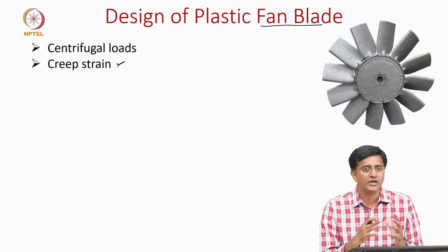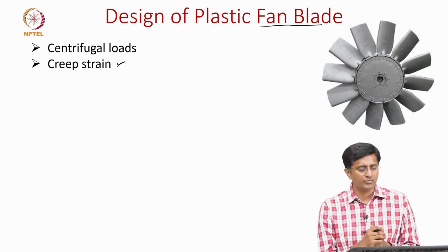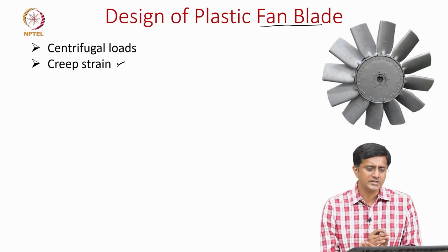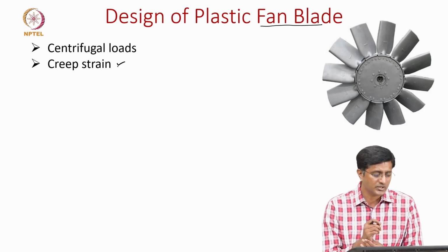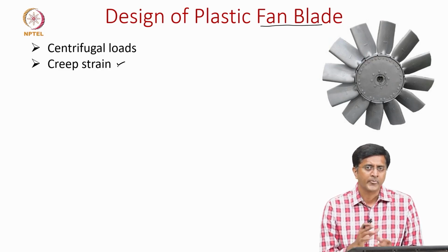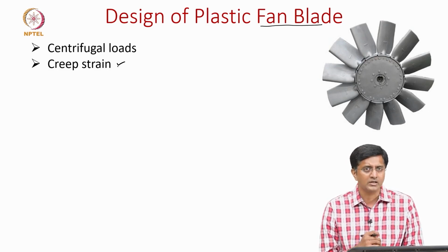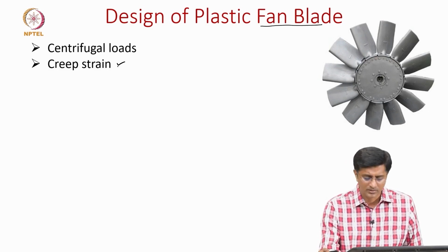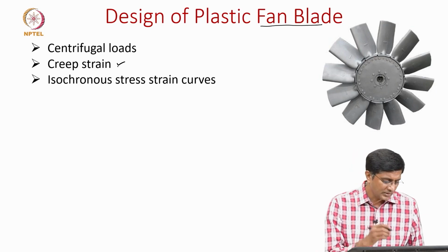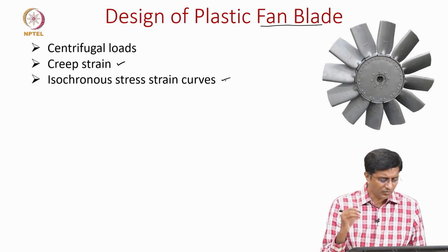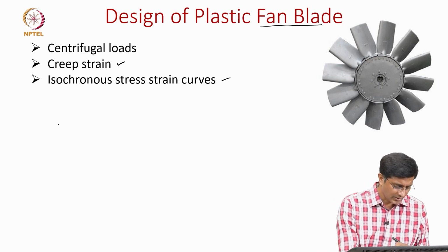Of course, by what we have discussed in the previous videos, one can apply the viscoelastic analysis and try to come up with the relations or equations to estimate this creep strain. But usually in the industry, there is an alternative approach of how to design in these scenarios. There, we use these isochronous stress strain curves. Now, let us see what I mean by isochronous stress strain curves.